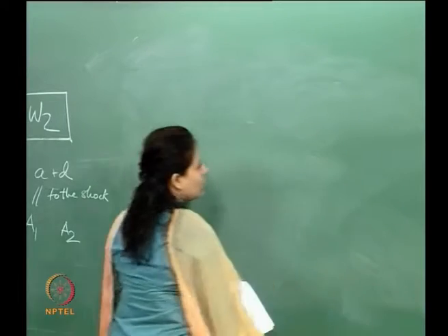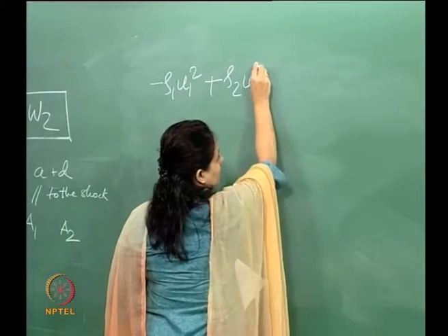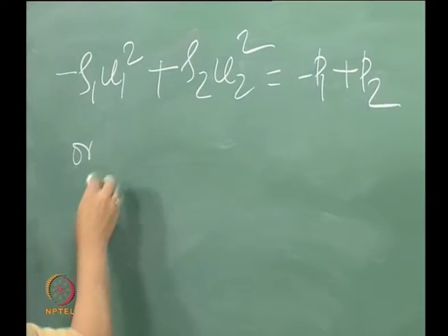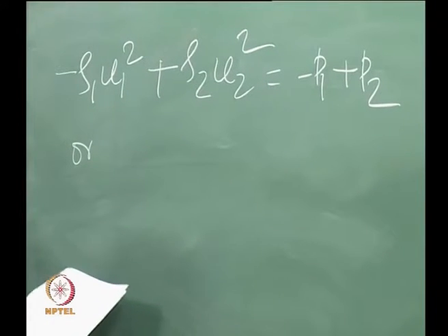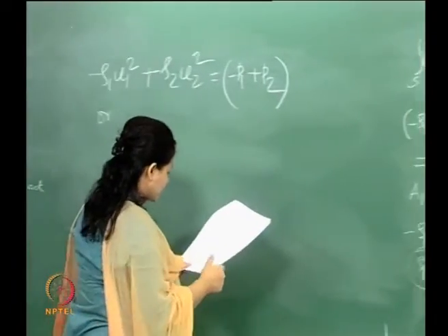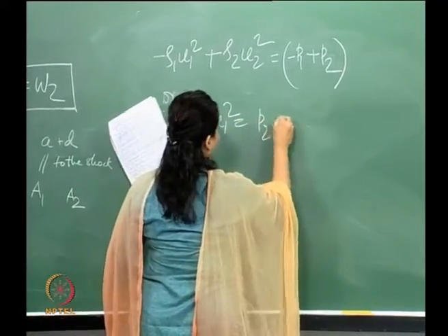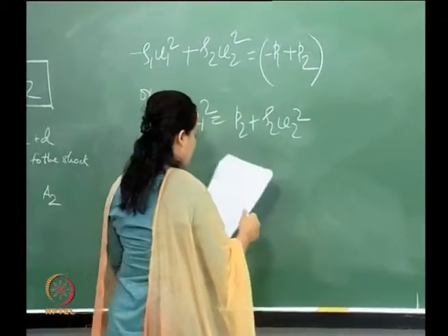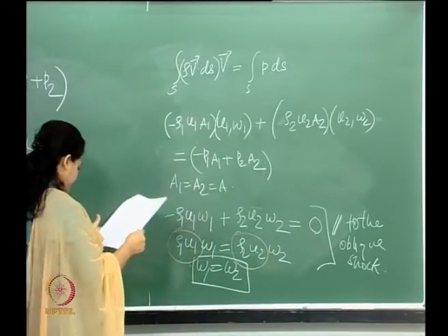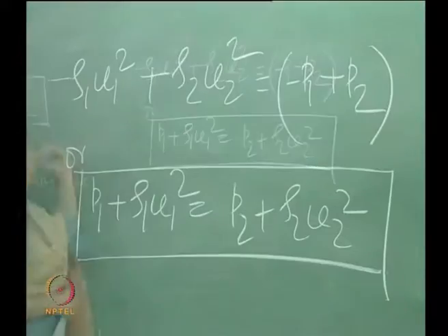So if I do the normal component, and work it out, we get this relationship, which is exactly the same as for a normal shock.